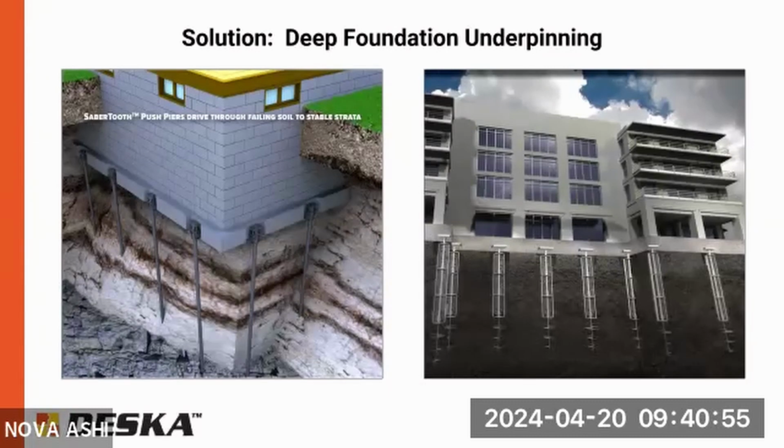Helical piers, they go by torque. When they get screwed into the ground with the machine, the torque is consistently measured until it meets a certain torque value, and that torque value actually correlates exactly to the vertical capacity of the pile. Again, a safety factor of 2 to 2.5 is used for helical piers to support a footing.